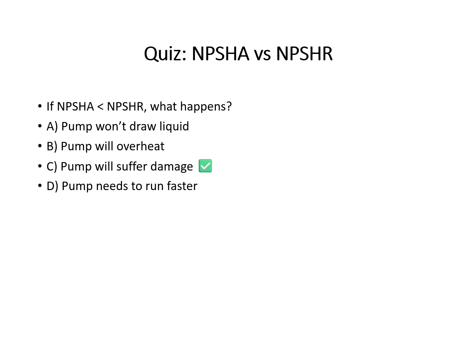So now let's go through quick quizzes. If net positive suction head available is less than net positive suction head required, what will happen? Sure, the pump will suffer damage, right? Cavitation.